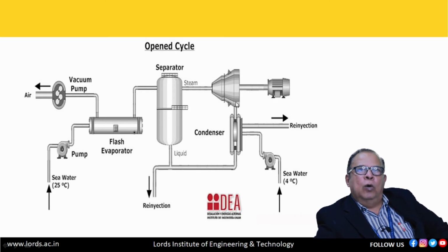Now the steam is sent into the condenser, and we know what is happening in the condenser: seawater at 4 degrees centigrade is supplied into the condenser, and this steam is condensed again. So steam is condensed into water, and then it is re-injected into the sea. So this is an open cycle system, and here this water which has been flashed into steam becomes pure water, because it has been made into vapor.